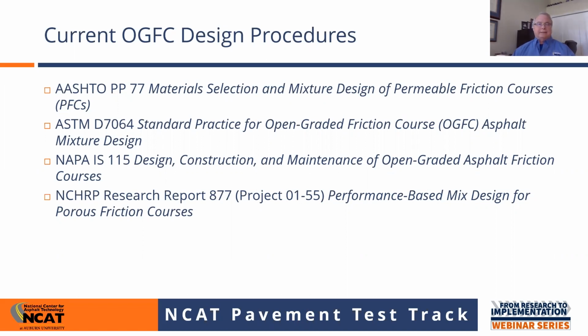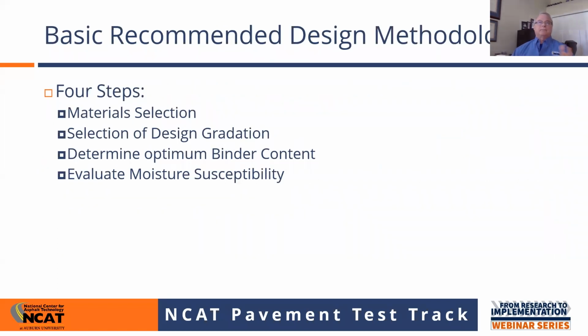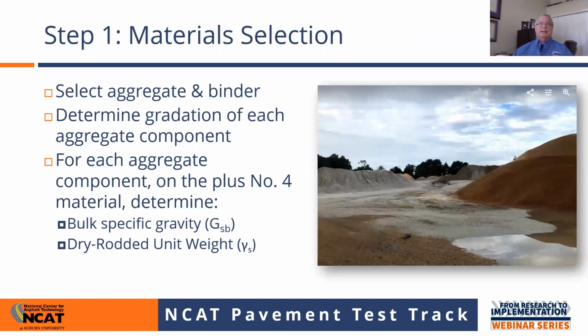So again, NCAT has a lot of experience dealing with open graded mixes, and a lot of states have a lot of research on open graded mixes. It's because open graded mixes, as good as they do for safety, can always be a challenge when it comes to performance. In the basic recommended mix design methodology that most design processes follow, it really boils down to 4 steps. You select the materials, determine the gradation of the aggregate blend, determine the optimum binder content, and then evaluate moisture susceptibility.